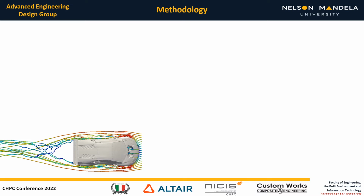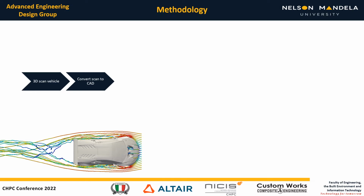My methodology for the project was as follows. Firstly, we had to 3D scan the vehicle so that a CAD model could be created. This was done using the Creaform Metroscan 3D scanner. Converting the scan to a usable CAD model was where most of the time was spent. After the model was converted, the mesh had to be created. Altair made creating the mesh and setting up the CFD domain a painless exercise, which was refreshing after the excruciating pain of converting the scan to a CAD model.